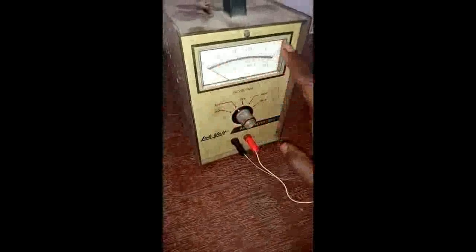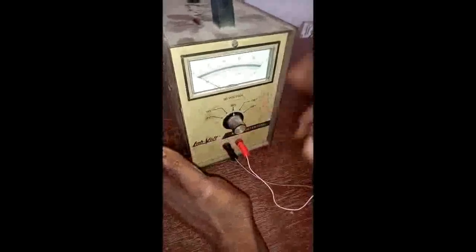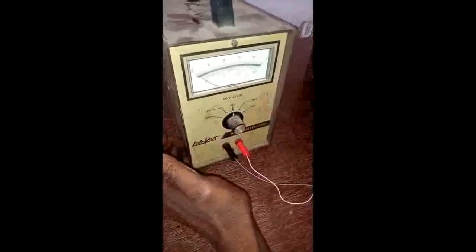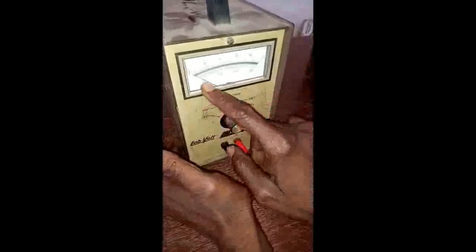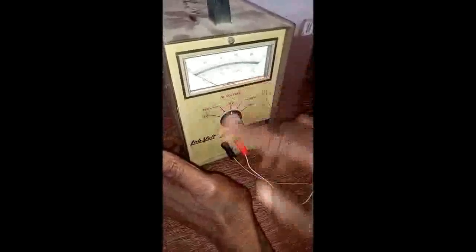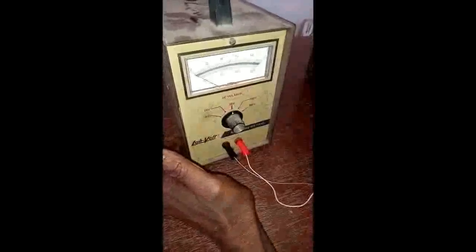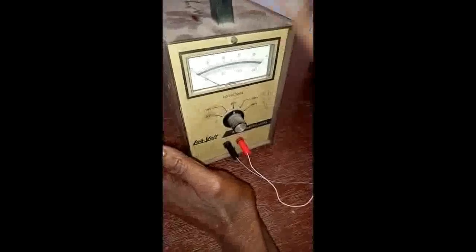Now, even if the manual asks you to use 0 to 10 volts, then you don't have any problem. You just use the upper scale. Because if this is 0, this is 1, this is 2, up to 10. Finally, if you are being asked to use 0 to 30 volt range, because there's no way you will not use any of these, either 3, either 10, either 30, then you just use the lower scale direct without any problem. That is about how to use this one.